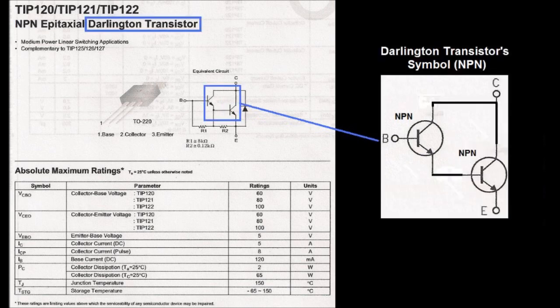Now we have the circuit. This shows it's a Darlington transistor. It's still an NPN transistor, but instead of having one transistor, this one contains two transistors inside, meaning that one transistor turns on another transistor. The circuit that I have circled shows a typical circuit that is the same thing as this Darlington transistor. If you didn't have this transistor, the circuit can be used as a substitute.